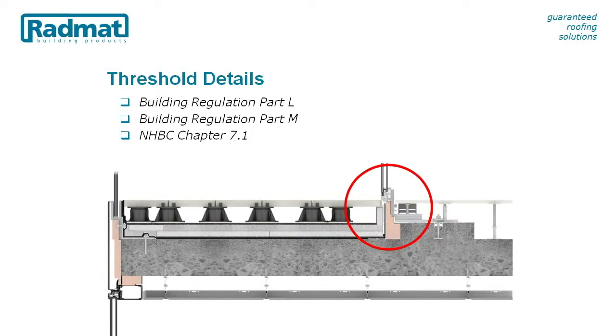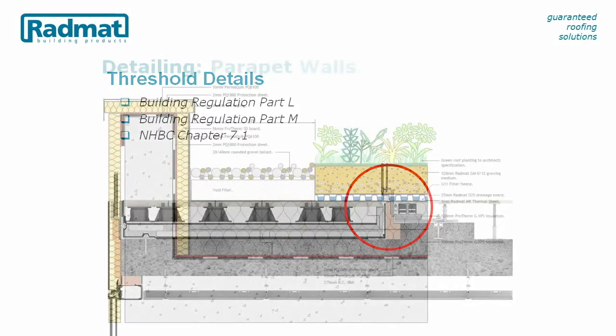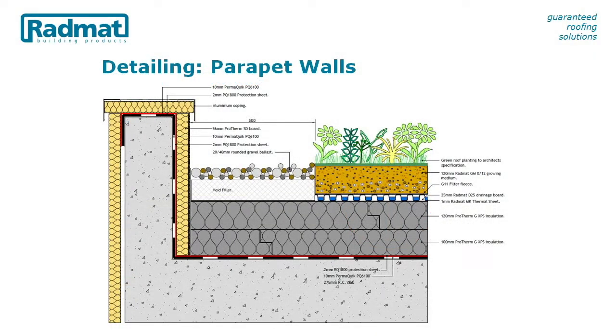In these circumstances, the introduction of vacuum-insulated panels has proven to be the only solution that avoids the condensation issues insulating in the ceiling void creates. Detailing at parapet walls is straightforward, with the upstands being installed first, overlapping onto the deck. The flat area is then installed to overlap the horizontal element of the wall flashing.